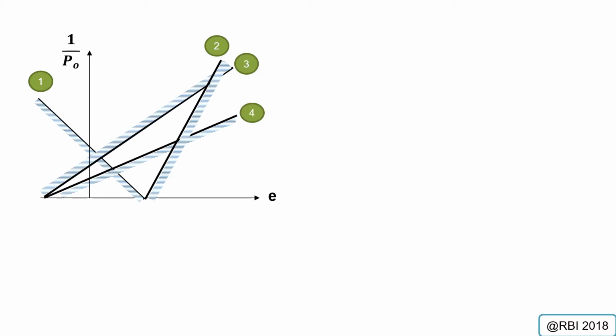So all these equations 1, 2, 3, 4 follow equations 12, 13, 14, and 15. The fifth line, which is the physical limitation, is where you put one line to represent any constraint that you might have for your eccentricity. With this bounded by 5 lines, you will see that the yellow area is colored yellow. That will be what we call the safe zone, right? The range of your pre-stress force and your eccentricity should be within that boundary. Okay.